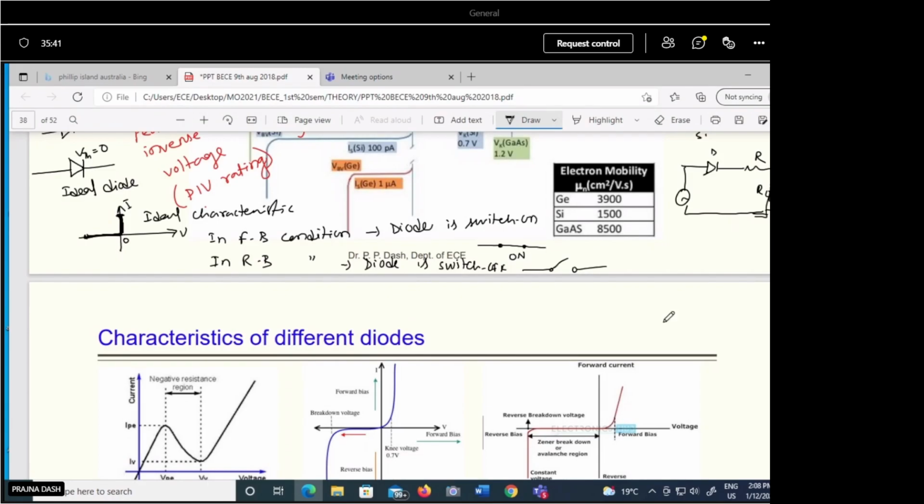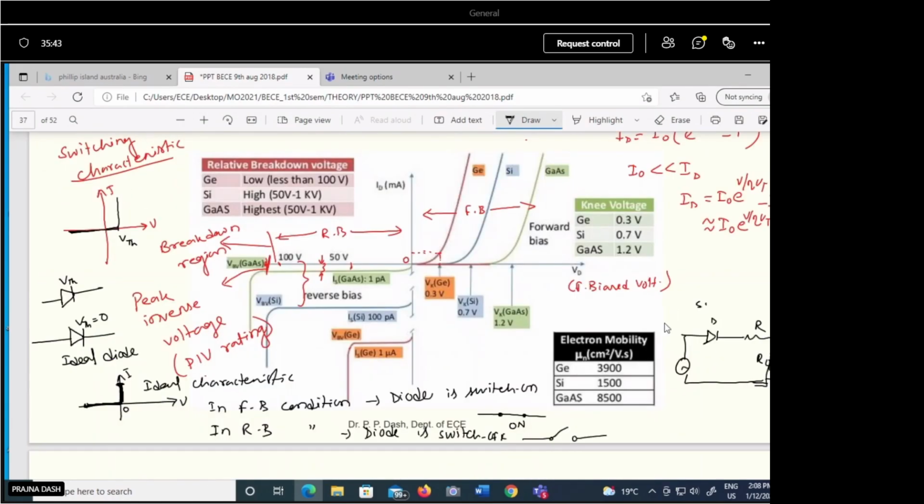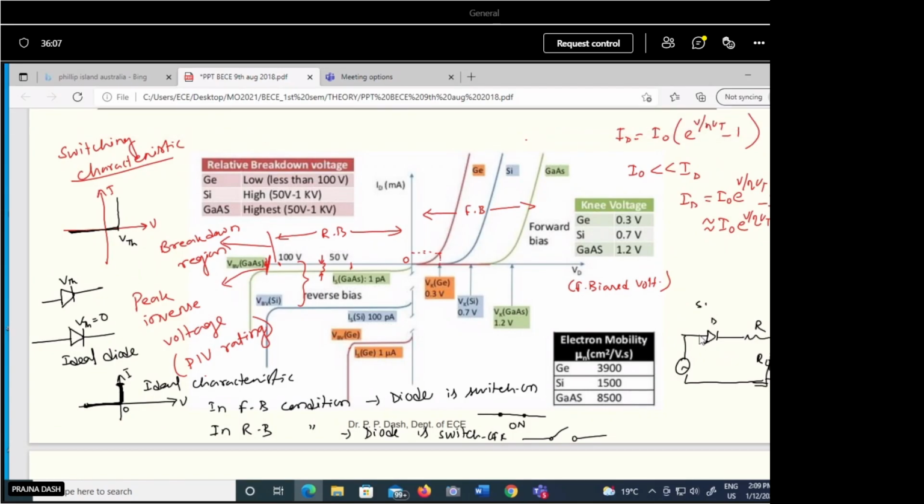Okay, so in this type of situation, whenever a diode is given and it is not mentioned whether it is a silicon diode or germanium diode, in that case you have to consider the diode as an ideal diode. In the ideal diode, you have to assume that when the diode is forward biased, the voltage drop across the diode is zero. That means you can directly replace the diode by a short circuit equivalent.